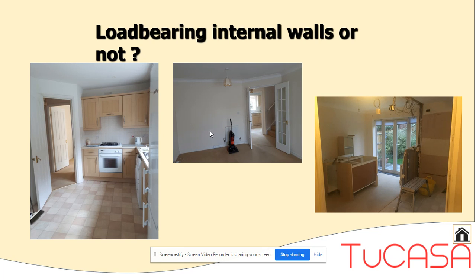So in this instance, somebody wanted to remove this wall between the kitchen and the dining room on the other side, and it was a lightweight partition, so they were safely able to remove it and extend through to provide a larger room. It's just an initial indication by tapping on the surface of the wall to see whether it sounds hollow or whether there's the dull thud of possible masonry, brick or block behind that plaster finish.